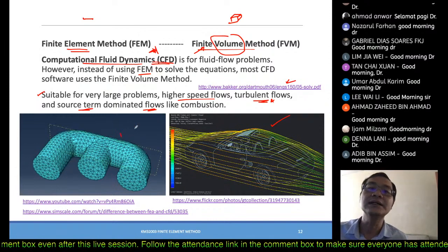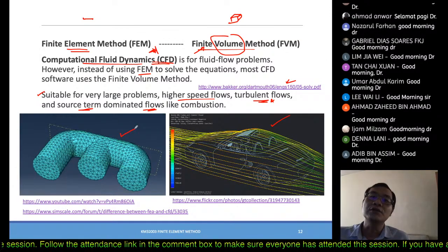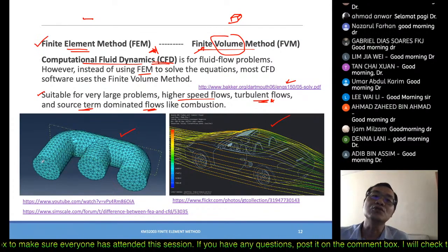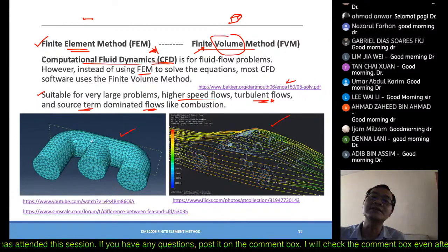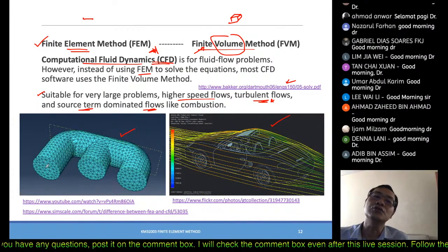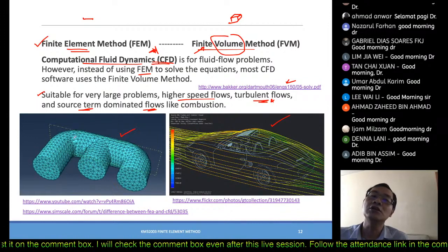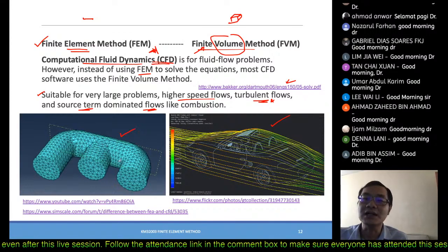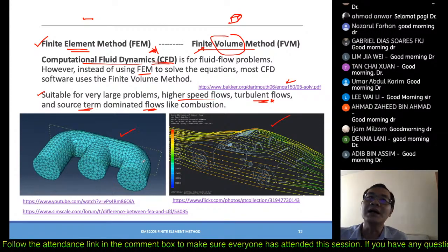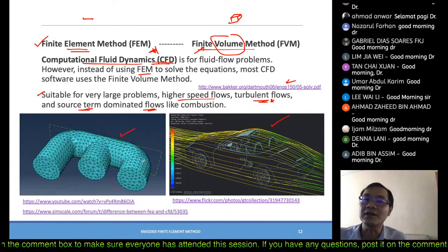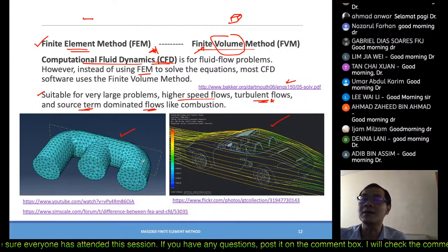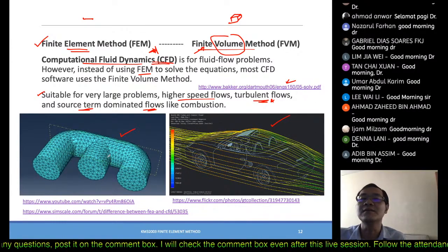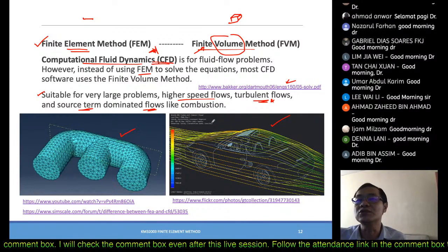So this is an example of how Abaqus, which applies the FEM methods, solves for the fluid. As you can see, the software requires you to model the fluid itself, mesh it accordingly and assign the fluid properties accordingly. If it is water, then you assign the viscosity according to the temperature and so on, and run it according to what you intend to do.